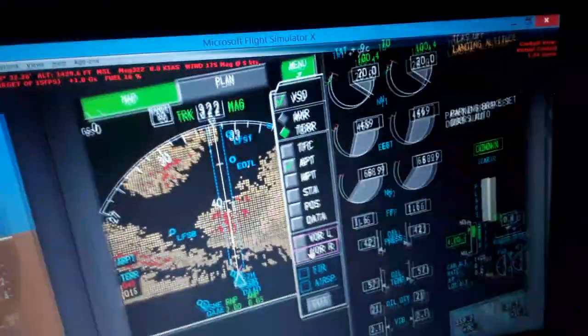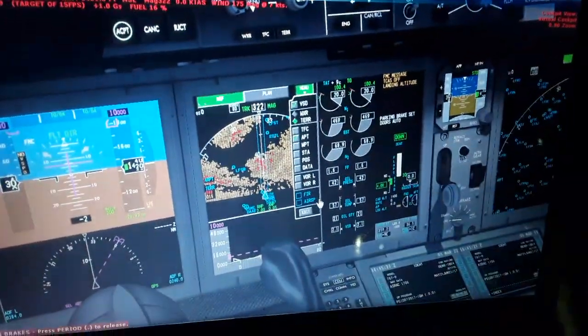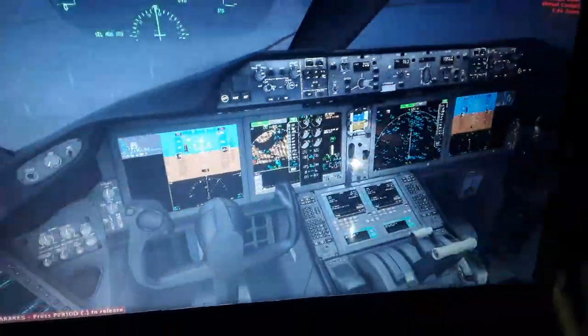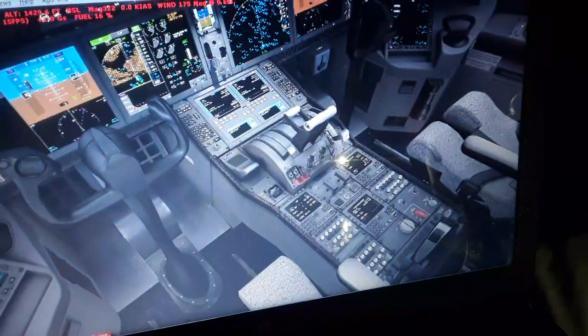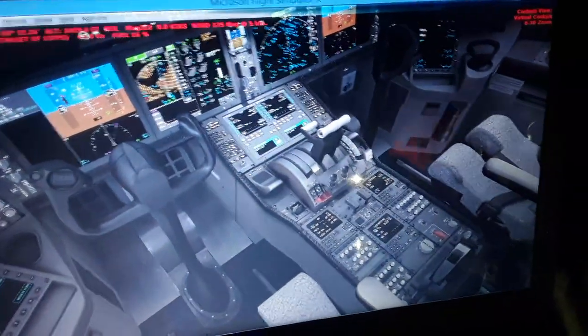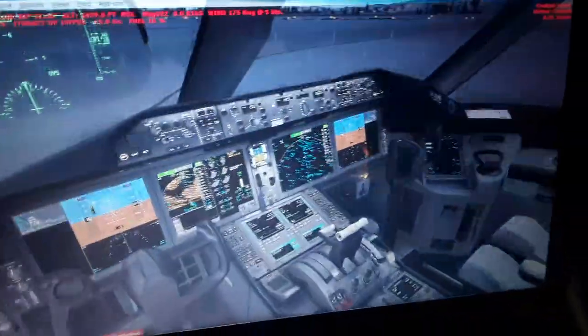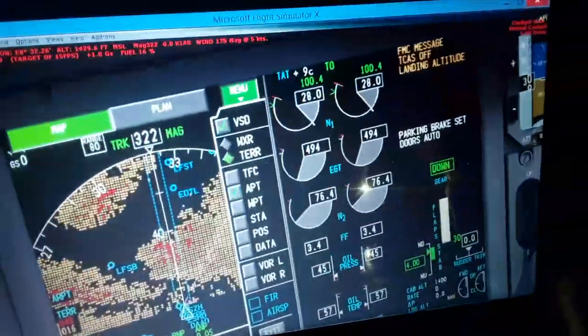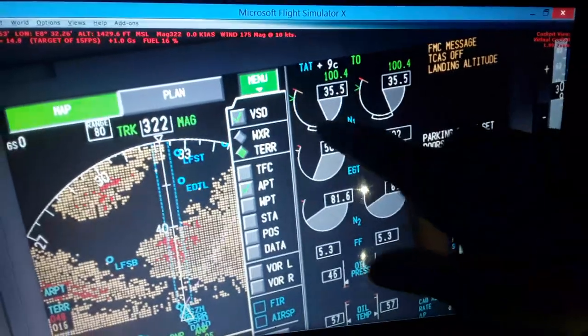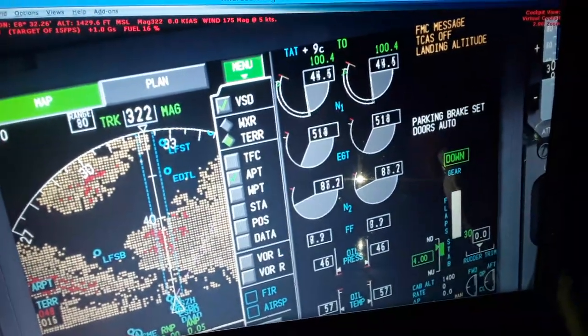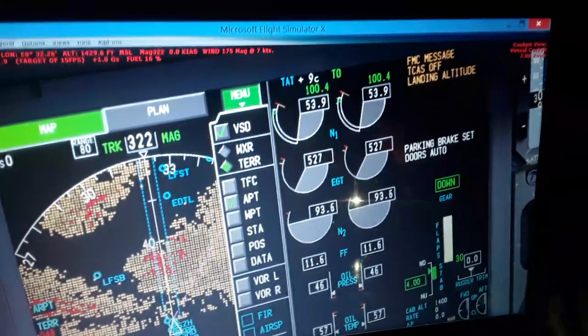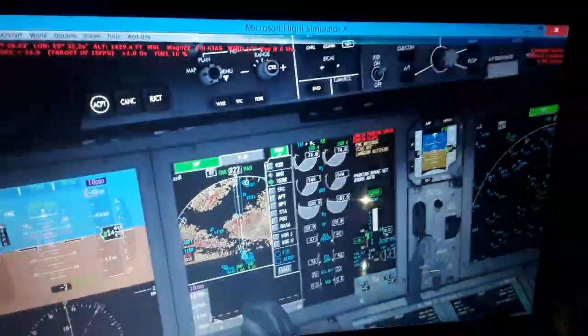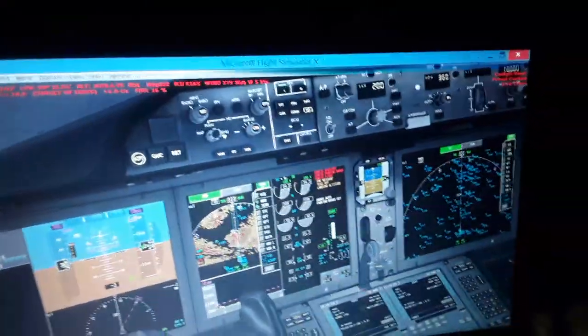So we have also the engines indications here. I will explain in a couple of minutes. So you can see the thrust levers when I move the engines forward. You can see the engines indication increase or decrease over here. So you can see the commanded position right now. You can use full takeoff. It takes like 3 seconds for the engines to reach the maximum takeoff.